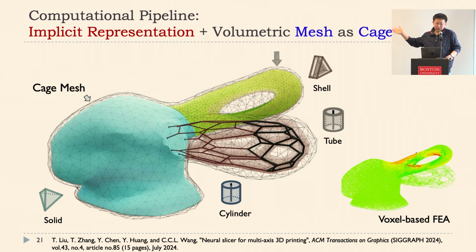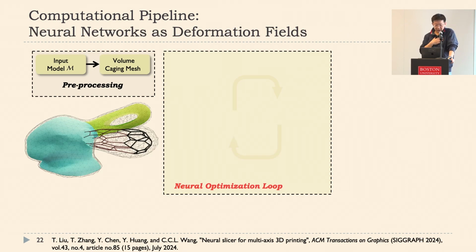And then finite element analysis can also be taken by the other representation. So basically, we're using the voxel-based representation to calculate the finite element analysis, which is actually a de facto standard of topology optimization. Many people use voxel meshes for FEA. With the help of that, we're able to generate FEA inside a voxel set, which is a scattered representation or sample-based representation of the tensor field, right? But at least we have some samples we're able to obtain. So starting from that, this is a pre-process. We have an implicit solid, which is embedded inside the volume cage.